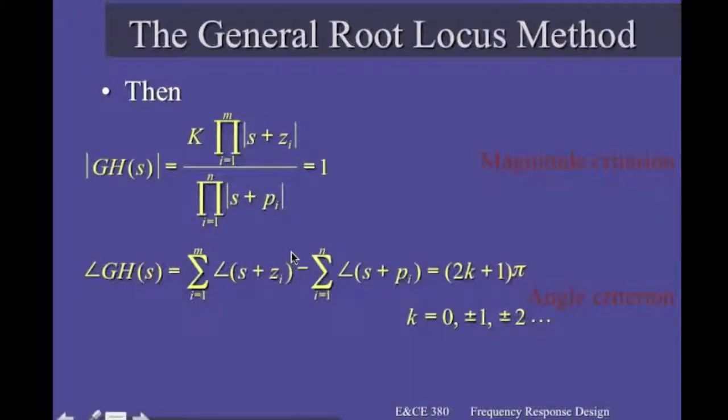These criteria are used in a more extensive way because they are used parametrically by changing K, so by allowing K to increase from 0 up to infinity. For each new value of K, you will obtain a new set of closed loop poles and a new condition to check for BIBO stability.